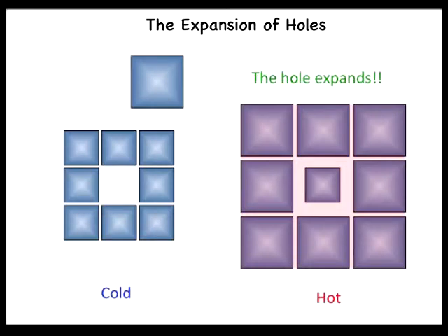When an object is made of a single material that expands when heating, the object gets larger, and all of its features, including holes, get larger by the same degree. Or, in specific regard to holes, we find a hole in a piece of solid material expands when heated and contracts when cooled, just as if it were filled with the material that surrounds it.